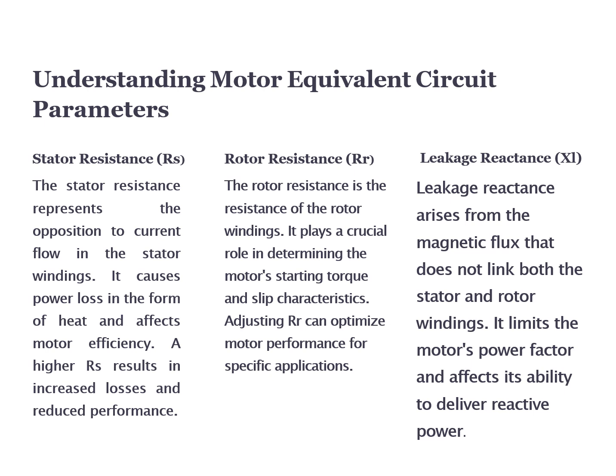First up, stator resistance. This is the resistance in the stator windings and it's responsible for power loss in the form of heat. A higher Rs means increased losses and reduced motor efficiency. So when designing or selecting a motor, keeping stator resistance as low as possible is crucial for optimal performance.